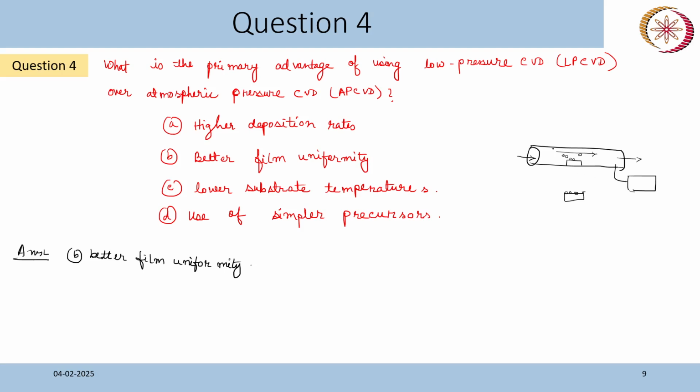Okay, so with a vacuum inside the chamber, that improves the distribution of the gases, so the gas will flow in a more uniform way. That will react with the substrate in a better way, because there will be less particles. It's not a very high vacuum.